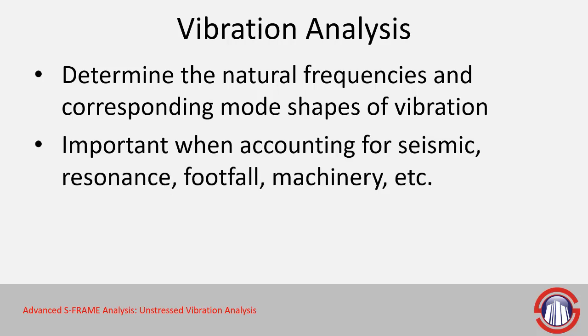This is extremely important when we want to look into further analysis that might consider seismic loading, resonance of some sort. We want to understand the resonance threat or footfall, machinery-induced vibration, you name it. Basically, any situation where we have some load that varies with time, it's very important that we understand the natural frequency and the various mode shapes.